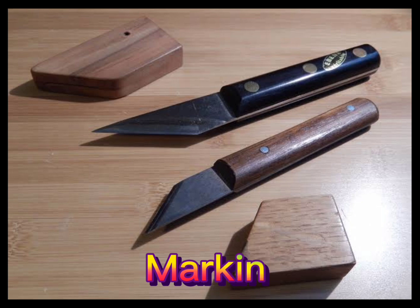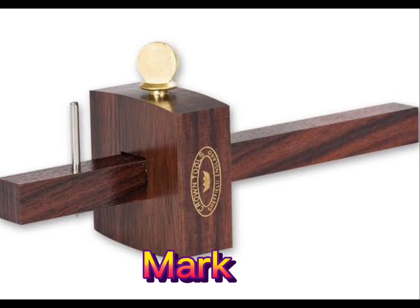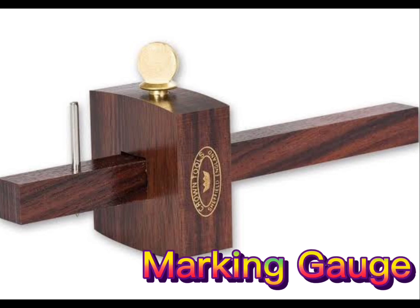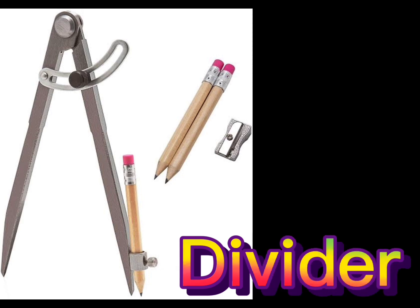Marking knife. This knife has a steel blade sharpened to a cutting edge held firmly in place by a wooden handle. It is used for marking off lines, usually across the grain of wood to be cut. Marking gauge. This tool is used to mark lines along the grain of wood to indicate the desired width and thickness of wood. Divider is used for marking out curved lines such as circles and parts of a circle joint. It is also used for marking equal distances along a line.